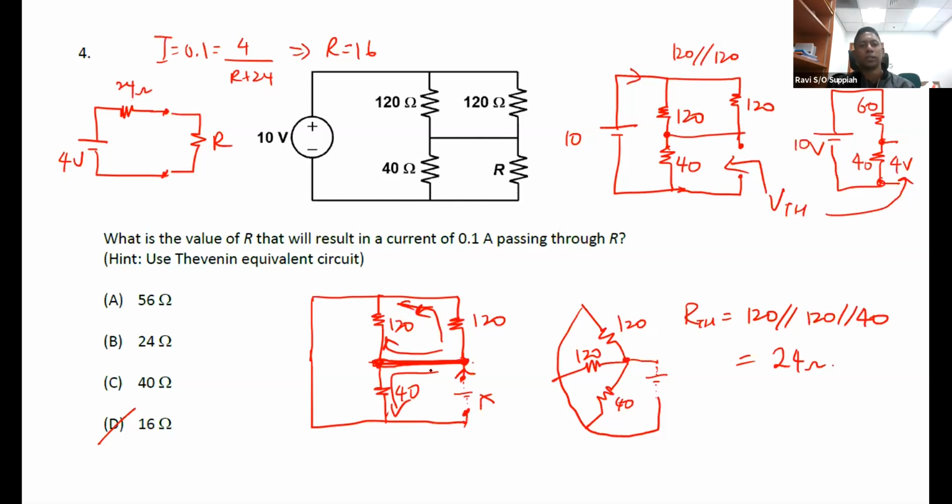For example, I mean it would be wrong to do it, but if I did a short circuit from here to here, then this line would create a short circuit from positive fully back to negative. I will create a pathway from positive fully back to negative, which means that the Thevenin resistance becomes 0 because there's no more resistance.